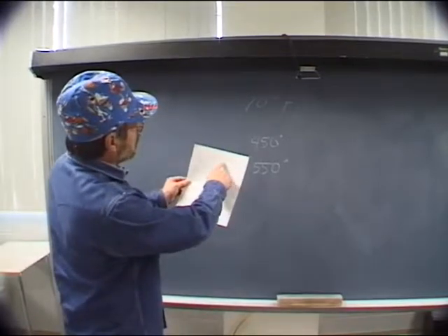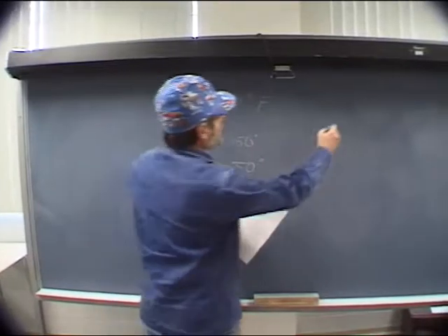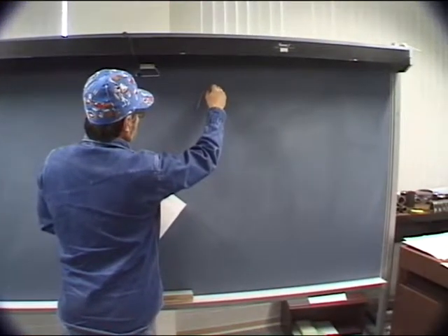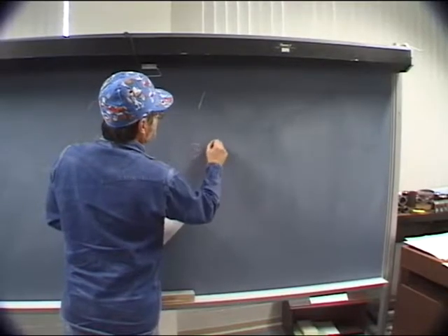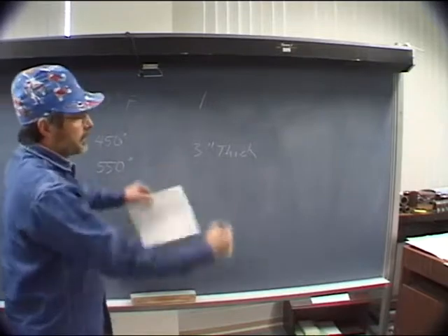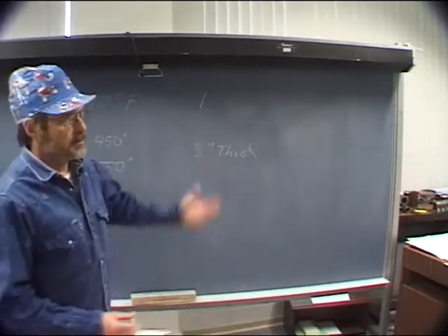Post-weld heat treatment, if we have any: what did we do it at? Typically, say you've got something that's 3 inches thick. Okay, you've got something that's 3 inches thick. Well, now that's going to require post-weld heat treatment. So the scenario we've been discussing wouldn't apply.